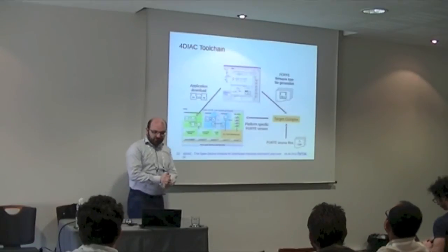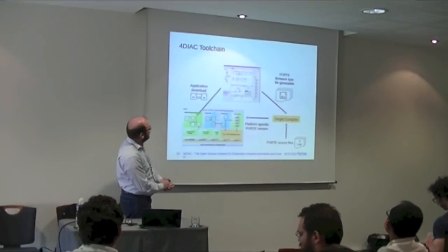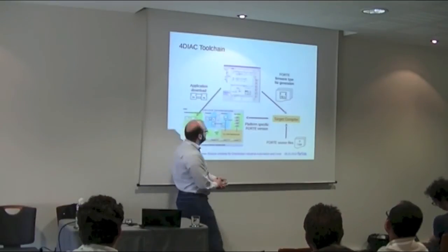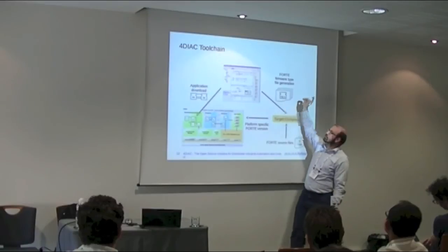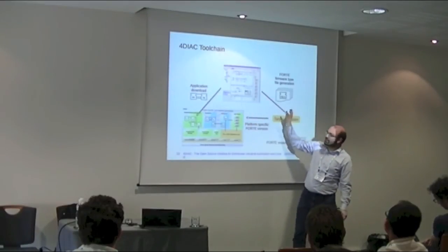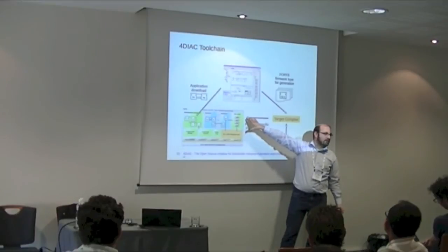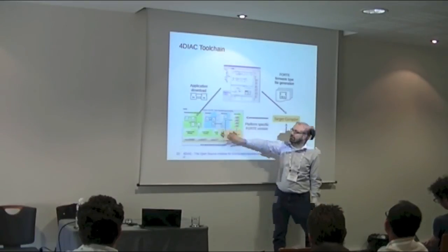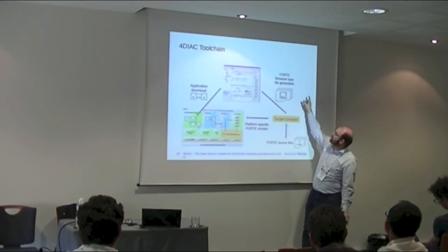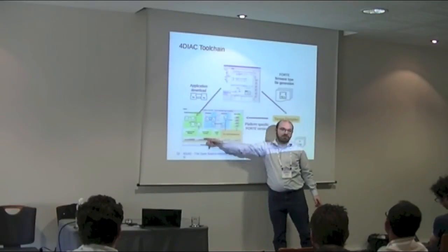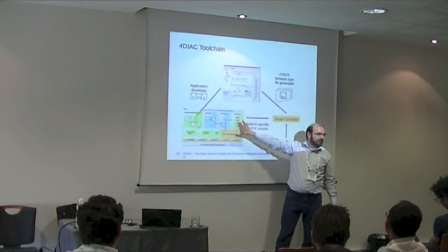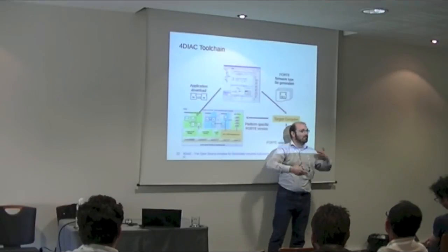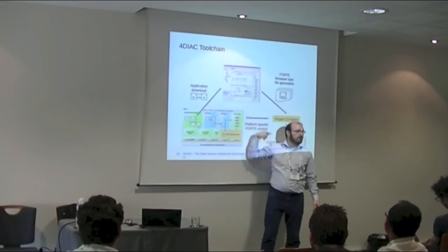Yeah, so how you would do this, what I've just told you. Currently, if you model something in your tool, one thing you have to know is that currently function blocks that you develop have to be compiled into the runtime environment. This is a little drawback because you have to rechange the flash file. So you take your function block, generate C++ code out of it, take the Forte with your target compiler, and you build something like the Forte. But the important thing is now, although you compile the Forte, you can download your applications, your connection information, your instance information from the tool, and you can change it dynamically.